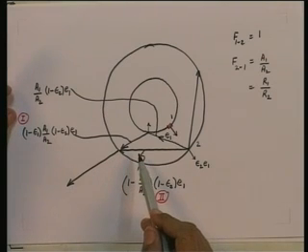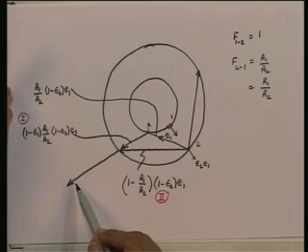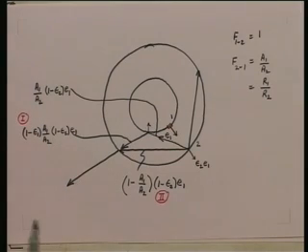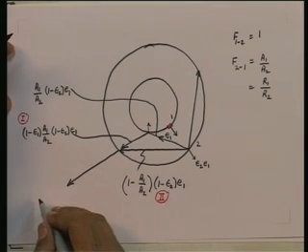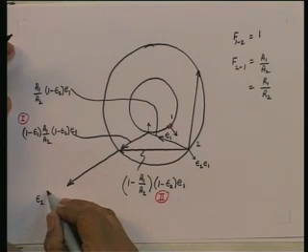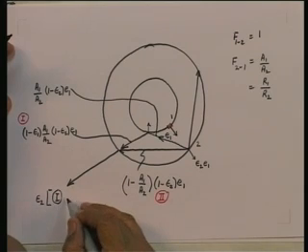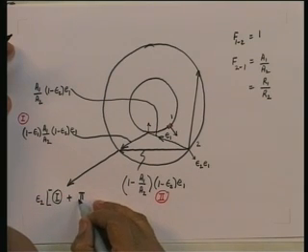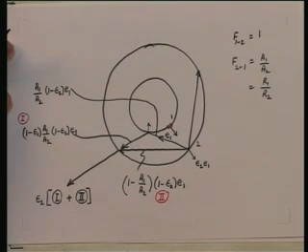If I multiply both of these by epsilon 2, that is the absorptivity of surface 2, I will get this quantity which is finally absorbed at the surface 2. So, I am going to get the big arrow showing the amount absorbed will be epsilon 2 in the bracket 1 plus 2. All right. That is what is going to be the quantity.